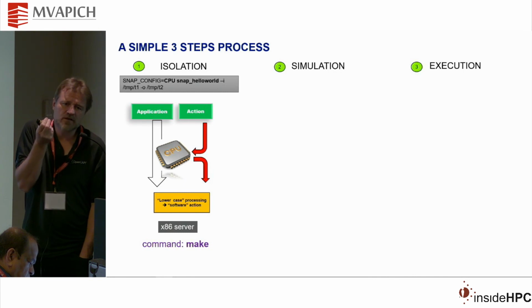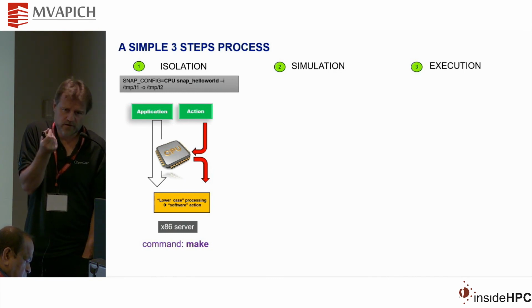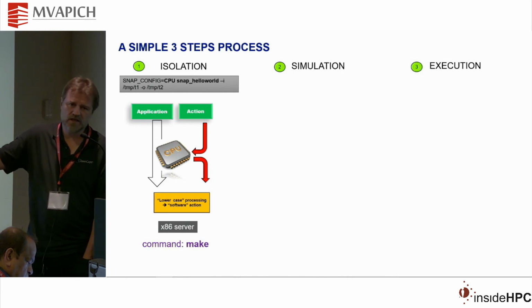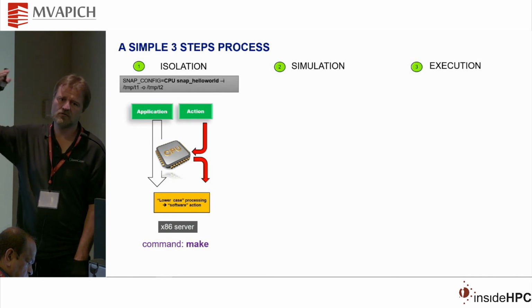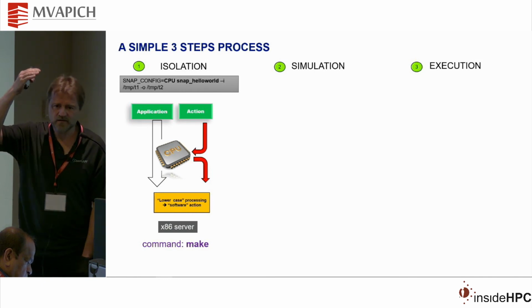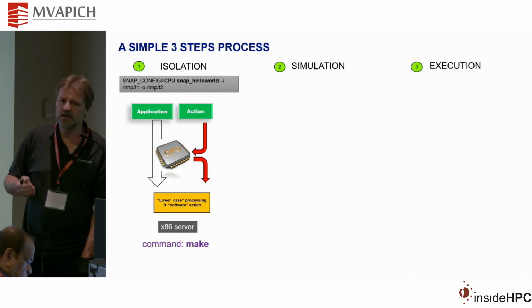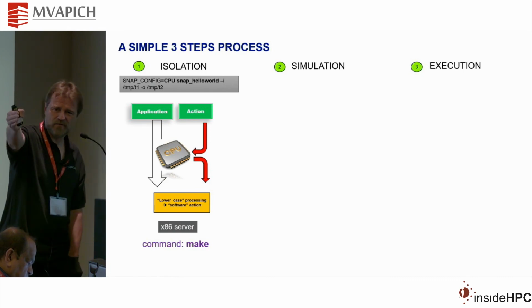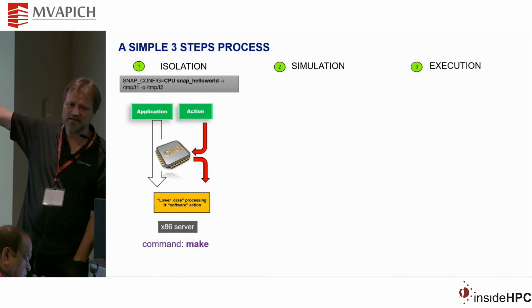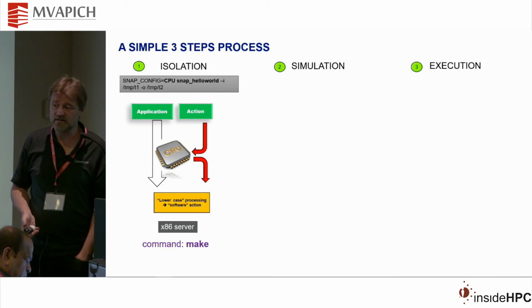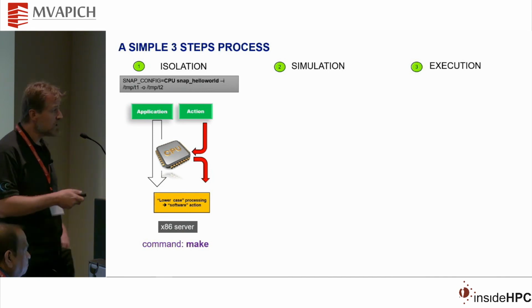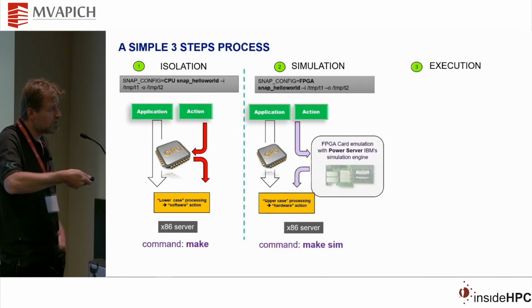We had to reroute this measuring factor a little bit so that the FPGA was not dependent on this time, because the FPGA has no means to know the system clock. It has no operating system working on it. It only knows how to get data from the memory, or from the system it has been attached to, the network or disk, but it has no means to access any operating system routine. Okay? So make sure you have a function that is standalone.